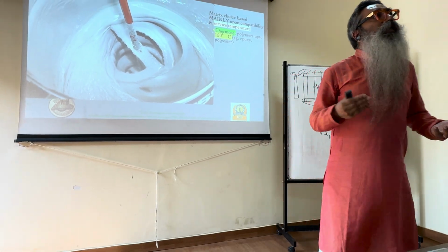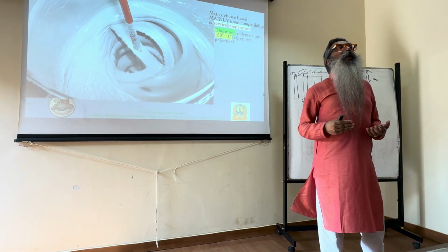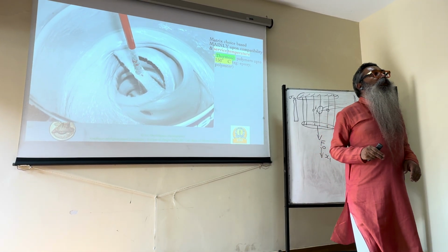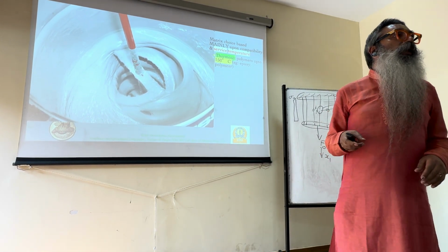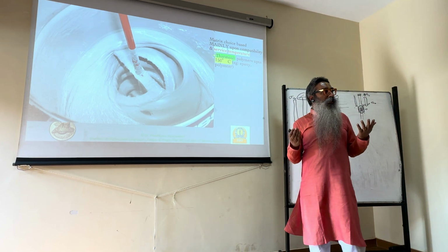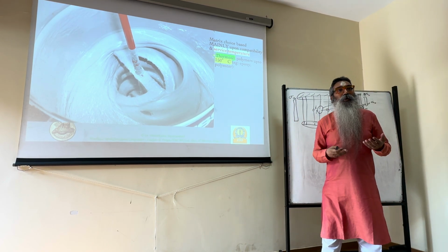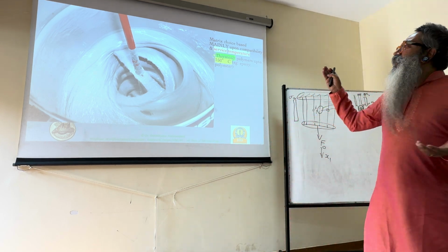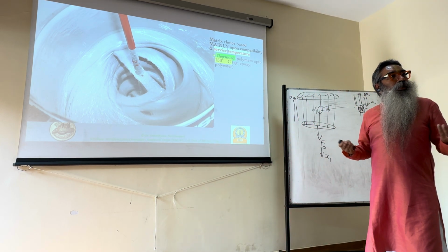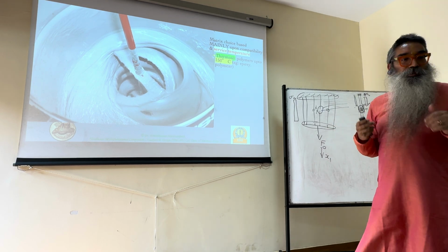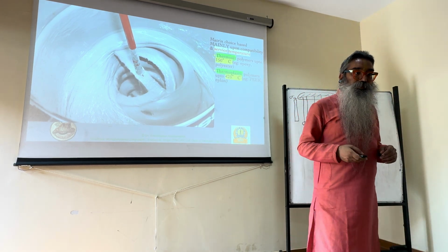Most of these will take you all the way up to 150 degrees centigrade and not more than that. So if your component is going to experience temperatures beyond this, then this is no good. But in most aerospace structural components, especially the primary components of the wing, the fuselage, the tail, etc., they typically do not go even up to this temperature. So therefore, thermosets were good enough, epoxies were good enough purely from this point of view.